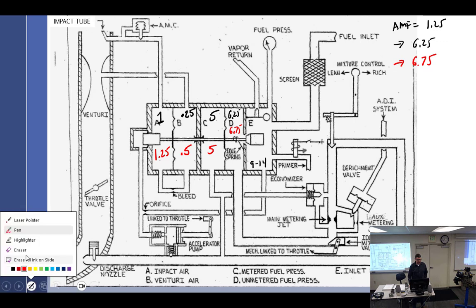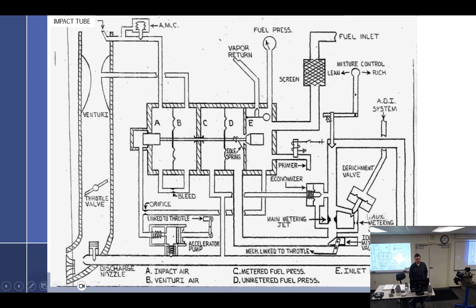Let's start with something easier. What happens if this diaphragm here ruptures? So what would happen to my air metering force? To what? I'd say it would be about 0, because it can't push to the right, it can't suck to the right, so it's 0.